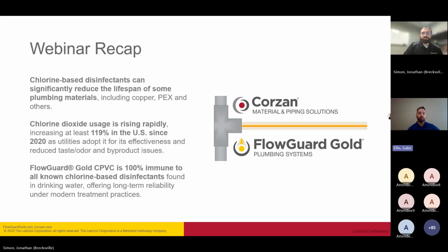But really to recap what we've covered today in our webinar, chlorine-based disinfectants can significantly reduce the lifespan of some plumbing materials, including copper, like what Jonathan talked about with chloramine stripping that internal patina away and creating pinhole leaks, PEX and other systems. Chlorine dioxide usage is certainly on the rise rapidly. It's grown 119% in the US since 2020.